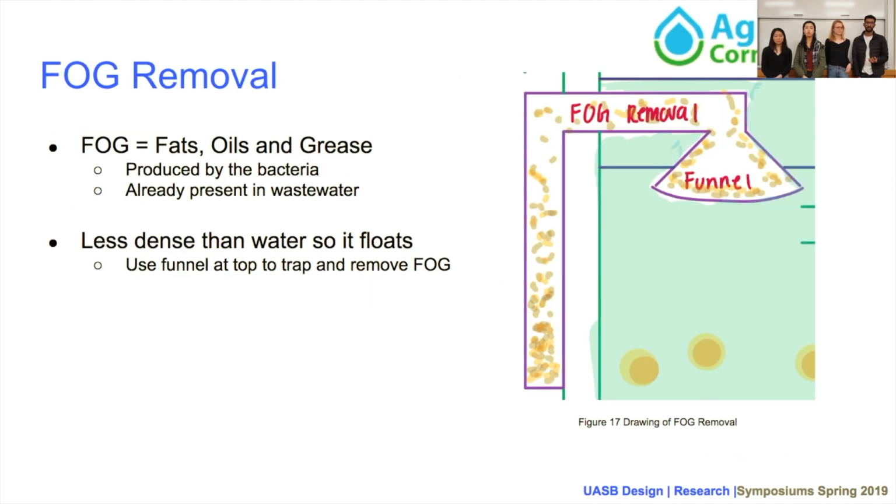So another component that we've added into our UASB reactor is FOG removal. What we realized is that in our initial large reactor, we were not taking into account fats, oils, and grease, which is what FOG stands for. So what we've added is this funnel FOG removal pipe. The bottom of the funnel will rest at the resting height of the water level within the reactor, so that